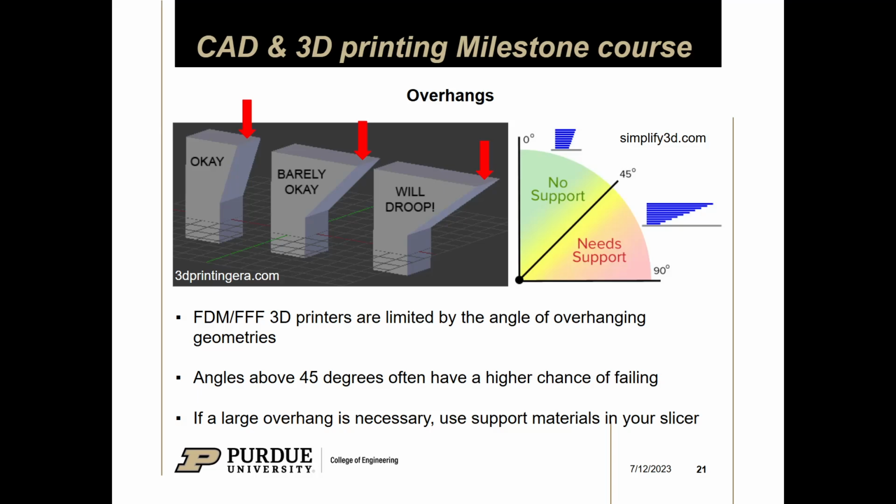Modern printers have gotten pretty good at cooling and printing overhangs. So if you have a really well-tuned printer, you can probably go more than 45, right? I can go more than 60 on my printer, but that's kind of pushing it. Depending on your hardware setup and what machine you're running, you definitely want to keep overhangs in mind. Again, typically the standard is 45 degrees, just because it's a nice middle between 90 and 0. So you can easily make these with a chamfer or something like that. So yeah, I recommend 45.